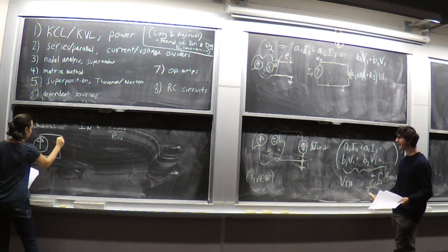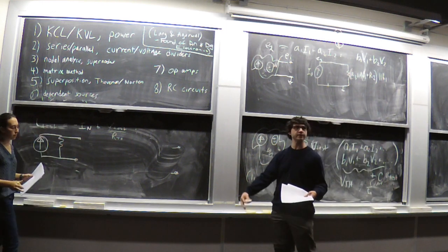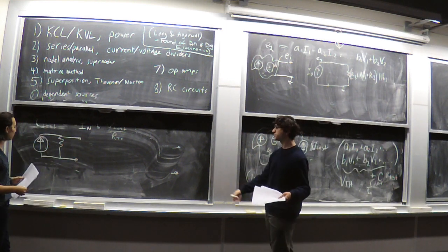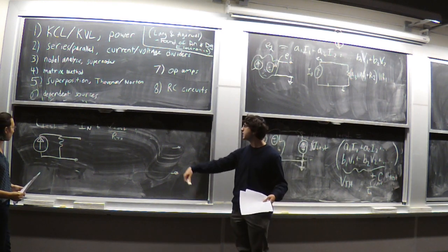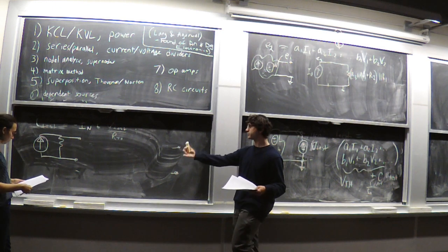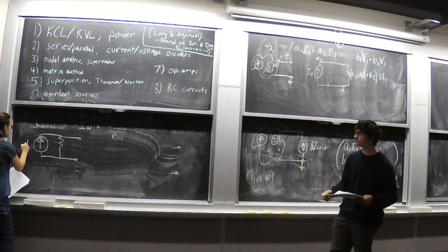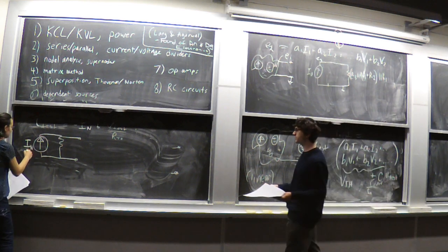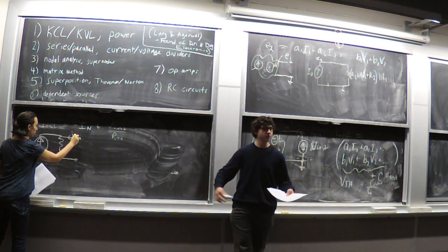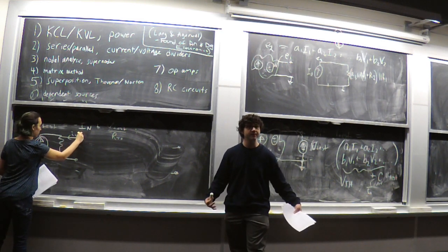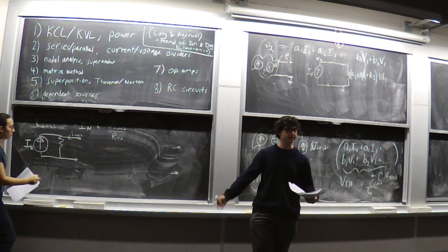And so the idea behind that is that now, instead of a voltage source in series with a resistor, we can also express the circuit in terms of a current source, the Norton current, in parallel with the Norton resistance. And it yields the equation that Hannah's just written. And one thing to note, which is very helpful, is that RTH and RN, the Thevenin and Norton resistances, are the same. Now, at first glance, that might seem like some happy miracle. You know, how did that end up working out?